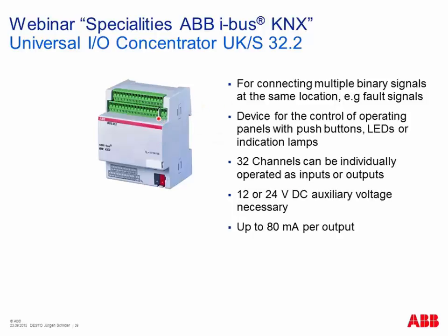And if you use channels as an output, you cannot connect directly a powerful load, no 230 volt load, because we have here a 12 or 24 volt DC power supply necessary. So it's made for connecting LEDs or any indication lamps or whatever with up to 80 milliampere.